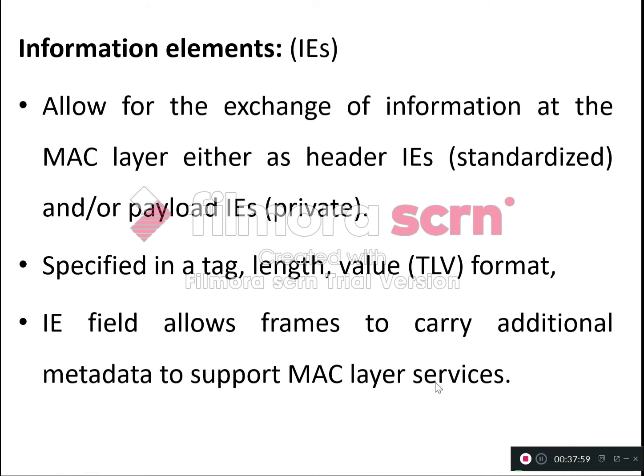The next enhancement is the information elements. In short, IEs allow for the exchange of information at the MAC layer either as header IE, which is a standardized one, or payload IE. So header information elements and payload information elements. Header information element is a standardized one and payload information element is a private one, specified in a tag length value format, TLV.